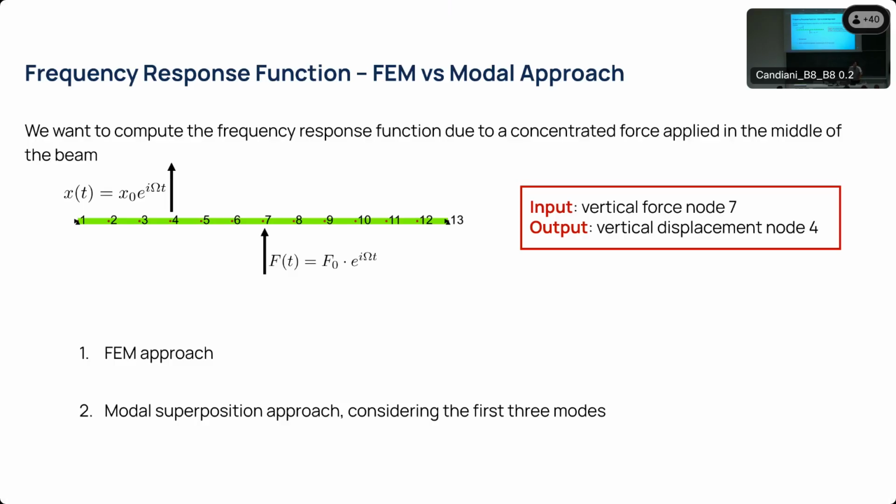Your computer starts working now, and maybe in a million years you will have the frequency response function of your structure. Those problems scale with the dimension of the matrices, so if we increase the dimension of the problem a lot, because it's a big structure, or because you want to do a very big analysis, or you are not very wise when making your mesh, you end up with a problem which takes maybe a couple of days to a couple of million years to be solved.